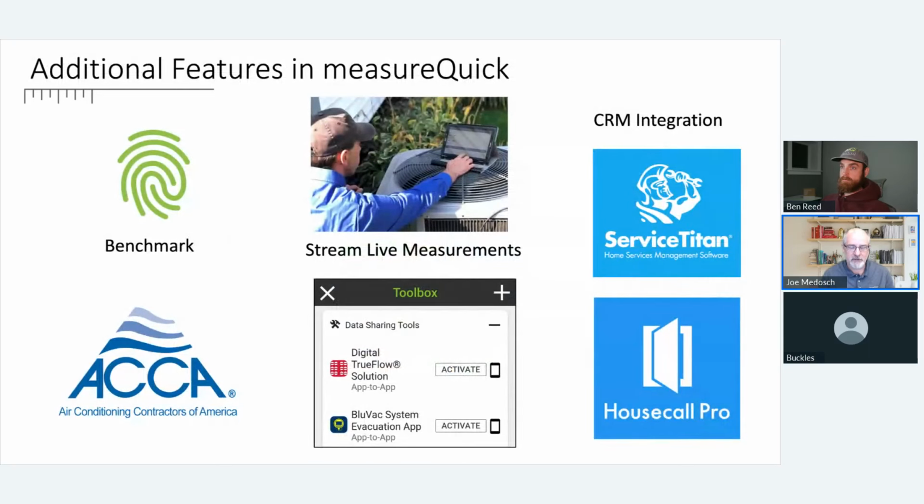So benchmarking is a fundamental part of measureQuick, and there aren't many systems that allow you to do anything like that. What we do when we benchmark is we go through and basically create a profile of what's going on. We're capturing the superheat, subcooling, the static pressures, the airflow, everything about this system is then benchmarked and locked in, knowing that when somebody comes back, they can actually determine that it was benchmarked and make assessments as to whether it's still operating within the benchmark. It's a crucial feature that you get. And again, this is one of the features you need when you unlock the system, right?